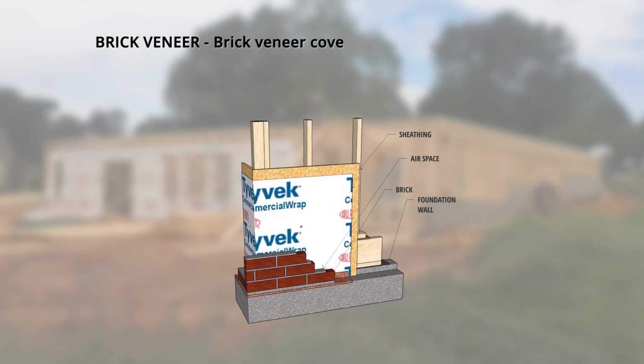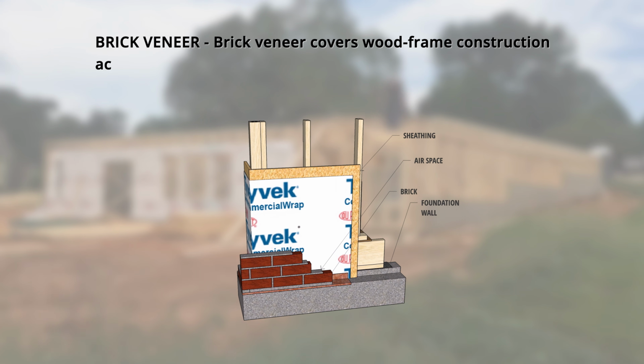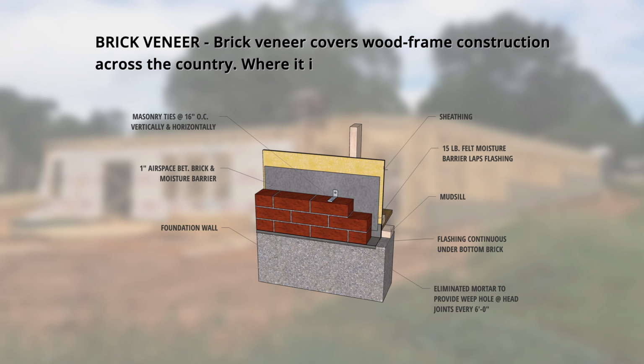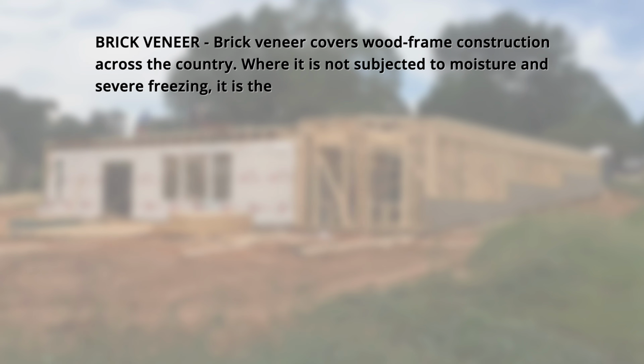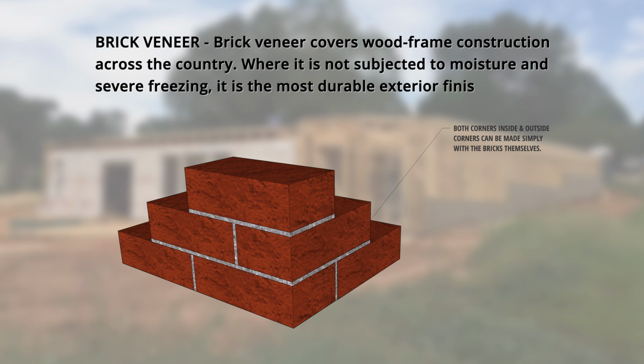Exterior finishes. Brick veneer. Brick veneer covers wood frame construction across the country. Where it is not subjected to moisture and severe freezing, it is the most durable exterior finish. Take a look at this detailed illustration here on the right.